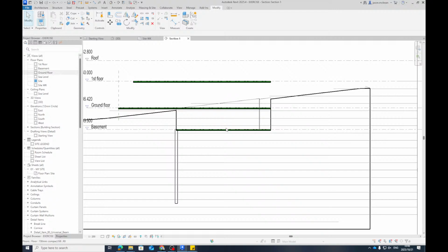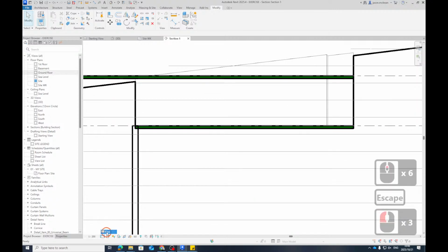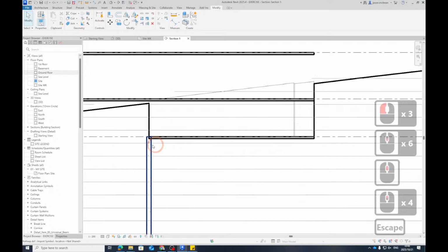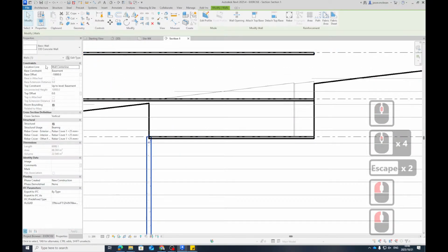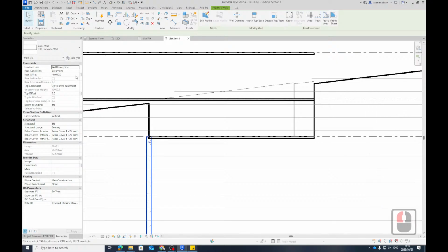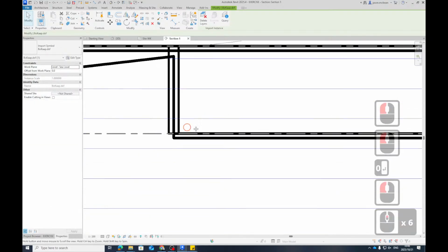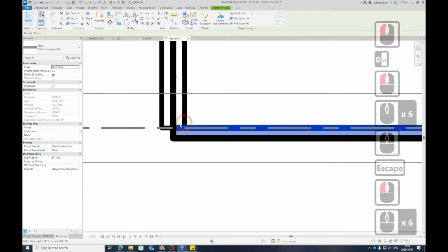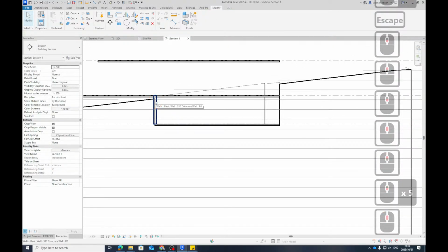Okay, so what I do is, I'm going to duplicate and switch this to fine, detail fine, so we start seeing the information clearer. Now your walls, these are always associated to something as well. So basement, so I'm going to make it go up to level ground, just to fix that quickly. You'll see this will start working and make the 0. Okay. So technically your floor slab can either go past, I'll show you in detail in a second, but I'll explain why I'm going to use a fill layer.